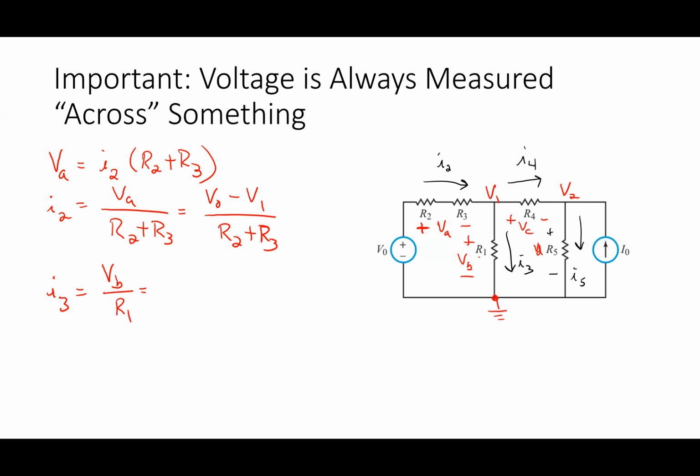In other words, I define my currents. You guys think I'm slow and you don't like to do it this way, but I don't make mistakes. Because what am I doing? I define the currents. I can write my KCLs in terms of the currents. I write the voltage across these things and I can track the passive sign convention and all that stuff.